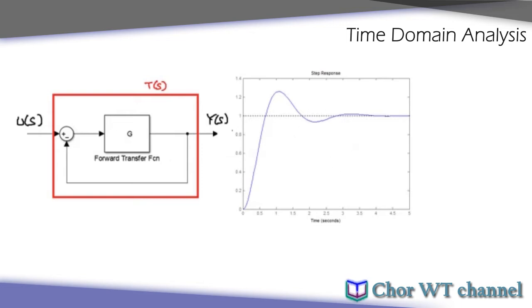Taking the normal case, we will take the input as a unit step input. So unit step input u(t) versus t, and the input will be just one straight line with an amplitude of 1. By supplying this input, which starts at t equals 0, we have an input of 1 supplied into a closed loop feedback with a unity negative feedback ratio. This one is 1, and we will produce an output like this.